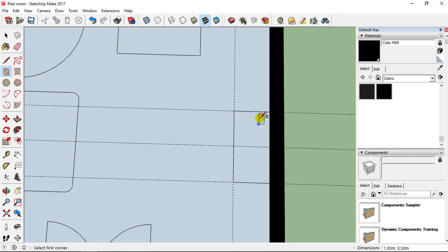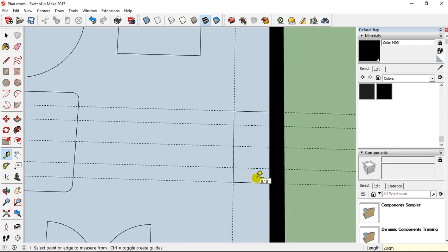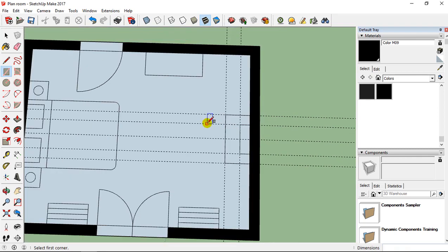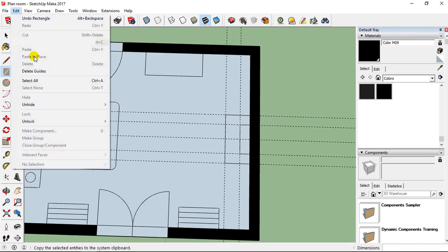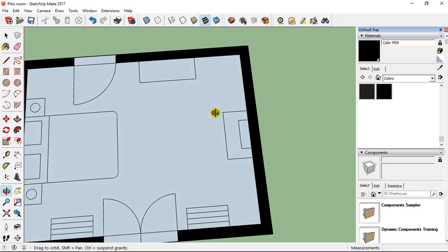After, for the style, I can also create another guide, and for example just to put one at 20 centimeter, another at 20 centimeter, just to show that you are going to add a TV, and here also one at 20 centimeter. And I take again rectangle tool and I add a rectangle like this. Then edit and delete guides, like that.